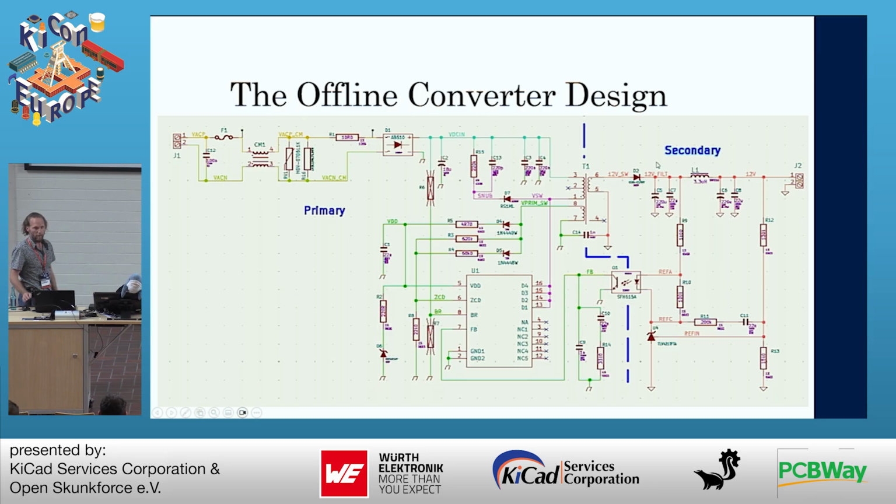where you create a low voltage. And then you need a large voltage clearance between the primary and the secondary side in order to create safety, so that your 220 volts electronics do not migrate into the low voltage electronics on the secondary side that is usually connected to any user devices. So for safety reasons, by law, you typically need a certain isolation barrier.